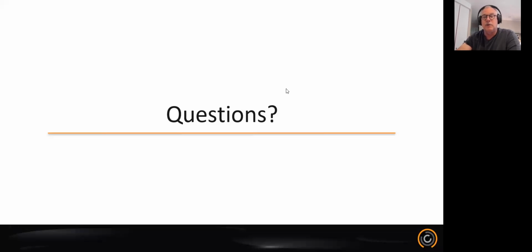I think the groundwater loads and hydrostatic loads are relatively straightforward for most people. And the variation in design really comes from how much live load you're going to put on top of that as part of the application. So I hope I answered that question. It was a good question to clarify.